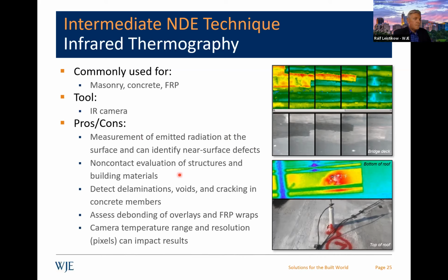And it can be used to find voids. This is actually a bridge deck. It can be used to find voids in concrete potentially. The thing you have to be careful of is when you do these types of readings, temperatures and things like that. As far as the heating of this, usually we try to do this work at sunset or sunrise. So you have a limited window because of the solar heating.